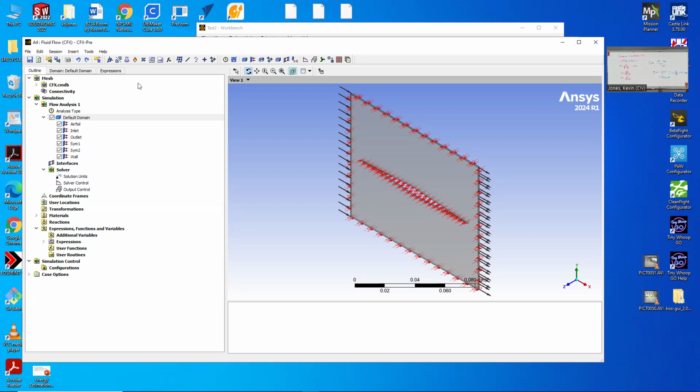The boundary layer is going to be so thin. Technically, it'll change the shock angle a little bit, but I think it's kind of lost in noise. You can try it if you want. You have to really pack in some cells, so the inflation layer is going to be ridiculously thin. So the cost of the calculation is going to be high.